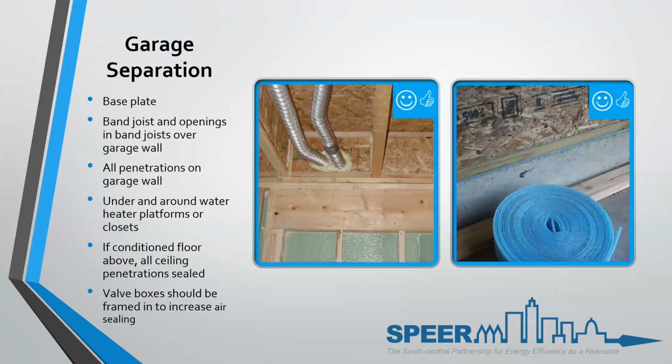And then Dylan says, is a tuck under garage still considered an attached garage if there is no door connecting the garage to the living space, like a garage has a unit above, but connected doors lead to unconditioned hallways? I would say that your only worry, and that's a great question, Dylan, the only worry is the floor above. If it's a conditioned floor above, you need to air seal that. It should have, in my opinion, a picture frame gasket around the bottom of all those band joists, and/or TJI banding or anything that's creating the separation, and separate that from the unintentionally conditioned floor above.